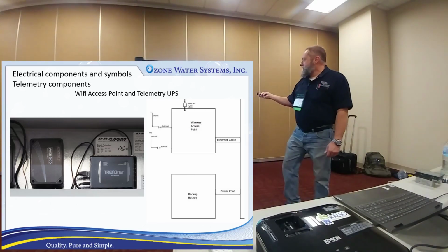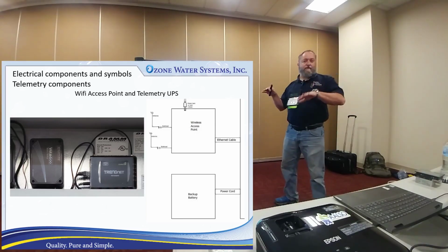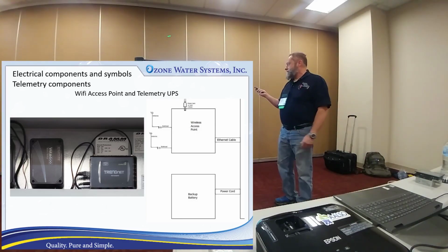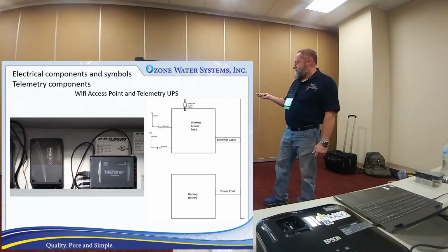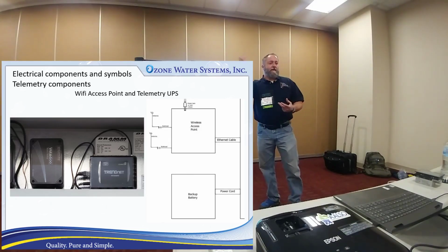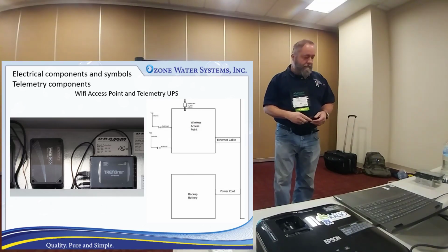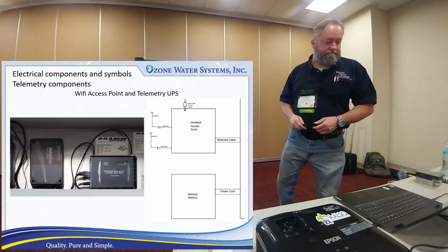There is a couple of antennas outside the box because this is a steel box, so you won't be able to get a signal out. So we put some bulkheads on there, and when you receive this one, you have to install the antennas on the outside once you get it, so they don't get broke off in transit.